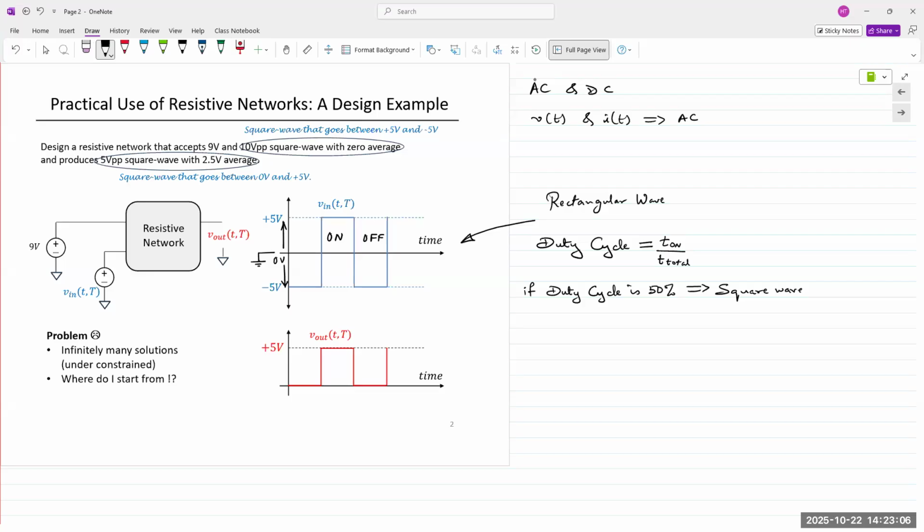So it is known as a 10 volt peak to peak waveform, P-P. If it just says 10 volts peak, 10 VP, that means it's only talking about one peak. If it's peak to peak and it's 10 volts, that means it's 5 above and 5 below. If it's 20 volts peak to peak, then it's 10 above and 10 below.